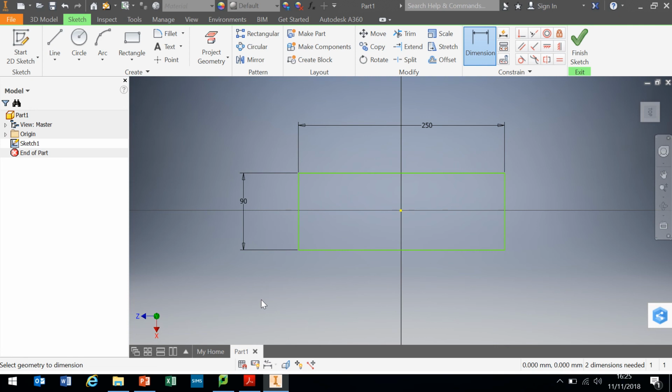So we now need to change this to look a bit more car-like. So I'm going to click line, and I'll select a line. Now I'm going to just draw a line to shape the back of the car. Where the line has gone yellow, I know that that line is going to attach itself to that line, and I'm going to do another line, and I know there that it's going to attach itself to that line. I'm not really worried about the size or the angle of the line. We're just doing this for a bit of style. Then I'm going to do another one to do the front end of the car like that, and right click to finish. Now we need to remove these bits here.